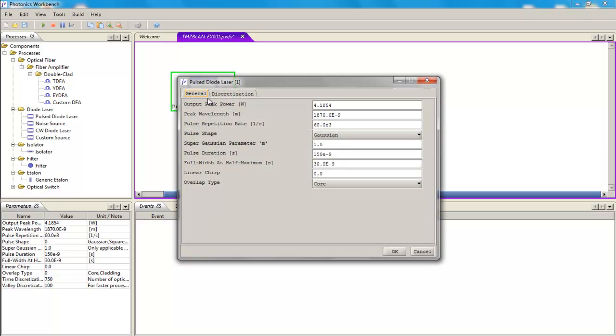This primary component has a comprehensive configuration template with respect to the time domain, a good candidate for dictating to the abstracted algorithms of all components how to represent time domain data during calculations in the simulation phase. Here, the pulse repetition rate is the inverse of the peak-to-peak time of the output pulse train, and in turn, this peak-to-peak time is the time window.